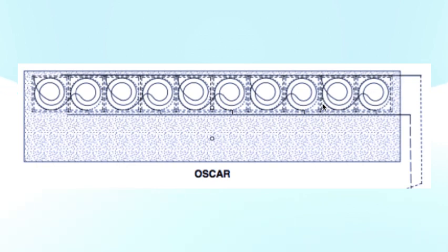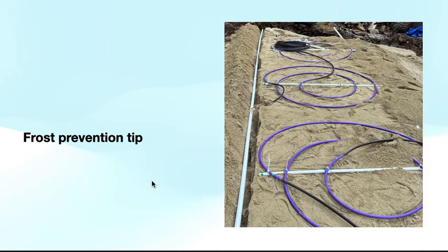But that connection, with the 2 coils together, I know that's what we've seen in the video and in this drawing, but it'll be different depending on the site. For example, if you only had 5 coils total in your whole drain field, each coil would have its own connection to the supply and flush. It wouldn't be connected to the coil next to it. So just need to keep that in mind and look out for that. But that's just a better illustration of all of that.